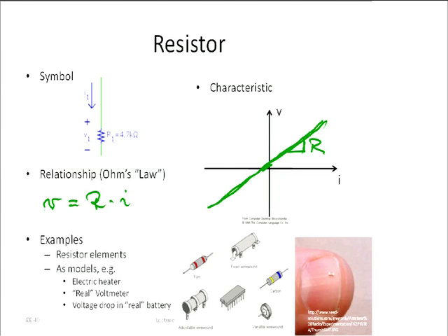Well, could be. I'm not sure whether this one is. This one, at least, is big and not adjustable. Why would you make a resistor big? Yeah, exactly. If this has 1 ohm resistance, and you put 100 volts across, there's a lot of current flowing, right? And then it gets really, really hot. Okay? So especially small valued resistors have to be fairly large so that the heat somehow can get away.